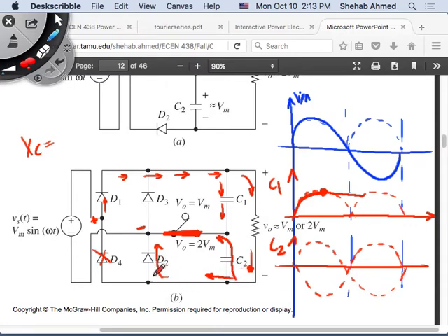then all the current will flow through the diode, because it will have 0 forward voltage drop, meaning there is no voltage that opposes the current flow. And as soon as current starts flowing through the capacitor, it will have an impedance. So current will choose which one is easier to flow. It will flow through the diode. So there will be initially some current flow through diode D2, only in transient, because what happens in the second half cycle? Second half cycle, what's happening?